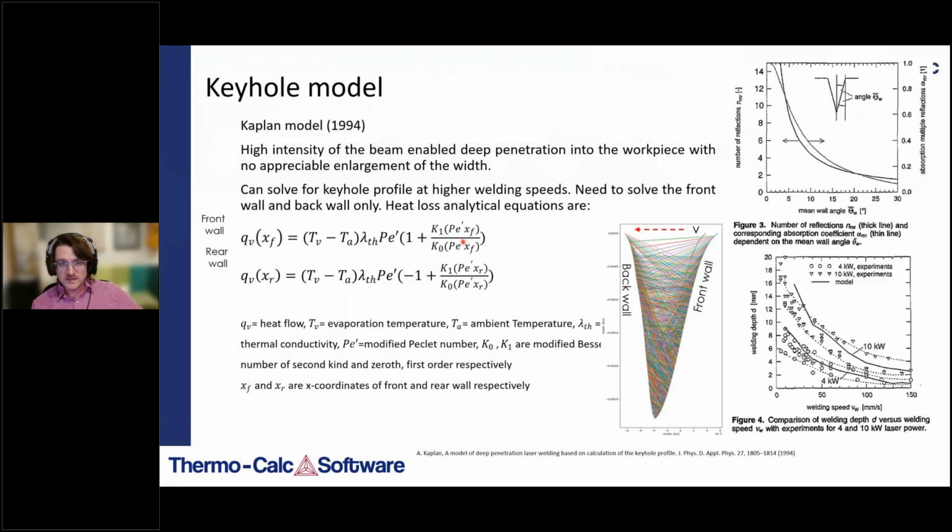that if we know something about the absorptivity, so we actually also have a model we've developed to calculate the absorptivity of the laser, because not all the laser power is absorbed, right? And then there are some reflections we're modeling in here where, there's the laser, what doesn't get absorbed is bounced back out, right? And then absorbed on the other side, and then bounced and absorbed on the front side, whatever's left until it goes to zero. We can calculate the keyhole shape analytically.